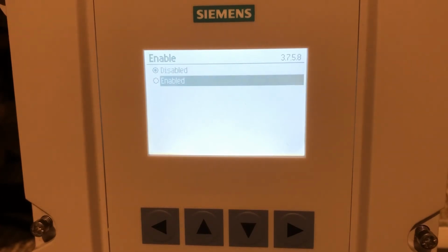As soon as data logging is enabled, you'll find that the other parameters are not accessible, because if we change the log, we can't do that in the middle of logging. So anytime a change is required, you'll need to disable the log and then re-enable it again.